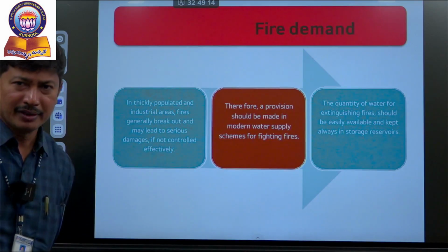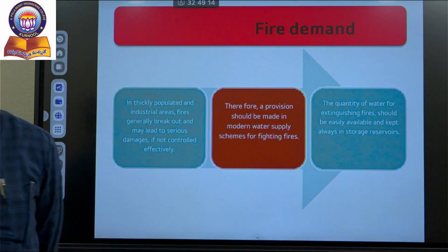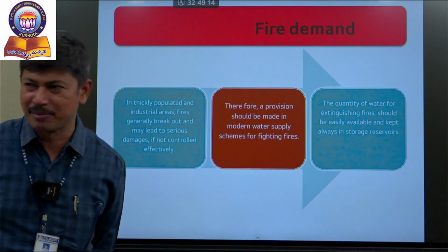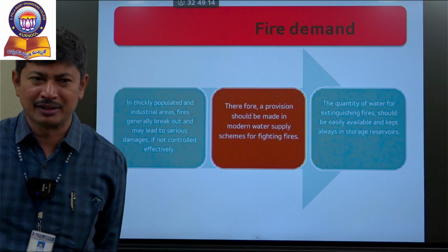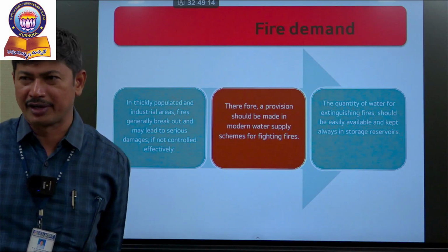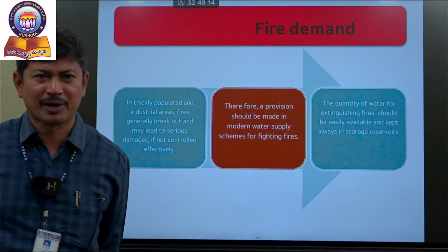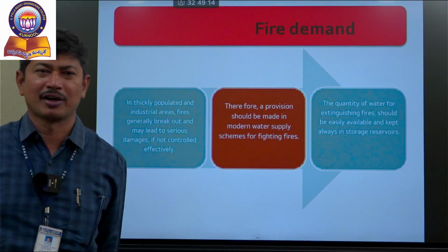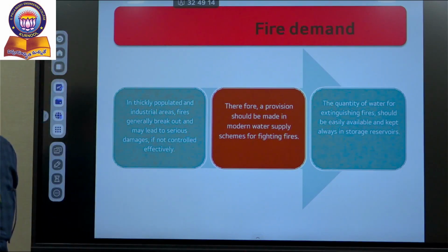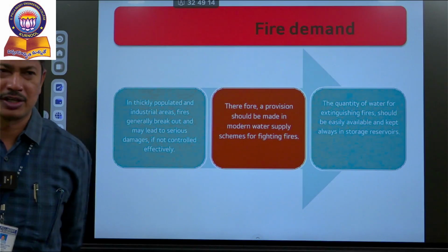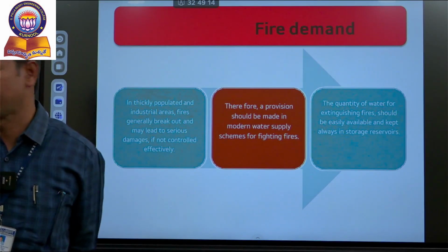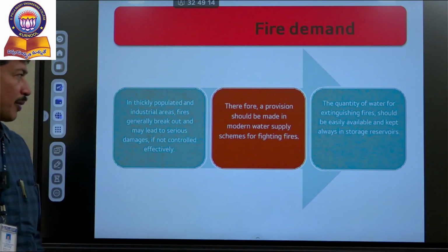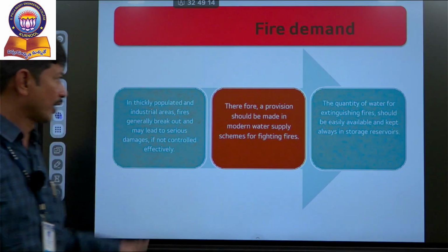Then fire demand. Water for fire demand is stored separately; it is not a daily demand. Whenever a fire occurs, we use that water for firefighting. Otherwise, if the fire is not controlled properly, severe damage occurs in thickly populated, commercial, and industrial areas. That is why in any town or city, some quantity of water is compulsorily stored separately for firefighting. That water is known as fire demand water.